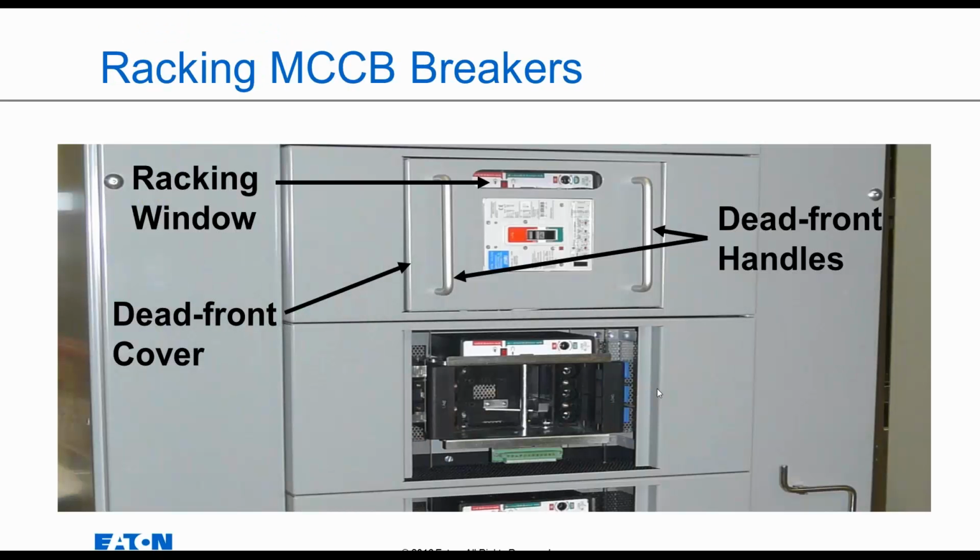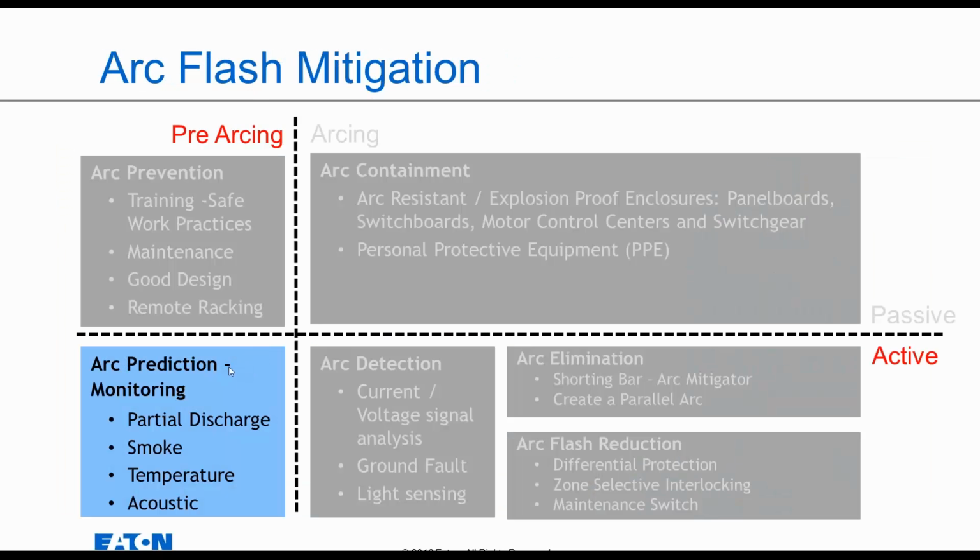And now low voltage power air circuit breakers and molded case breakers have racking capability, so you don't have to unbolt those devices either. Racking mechanisms are available.